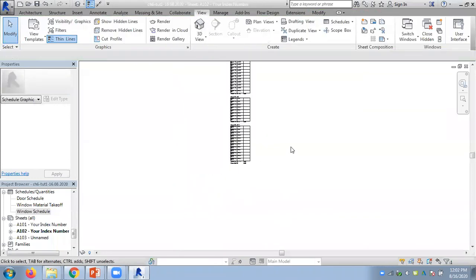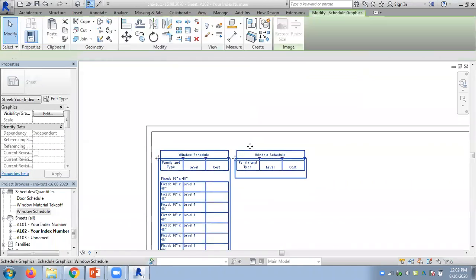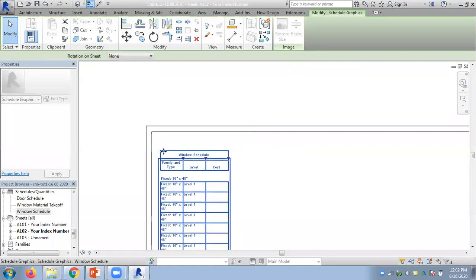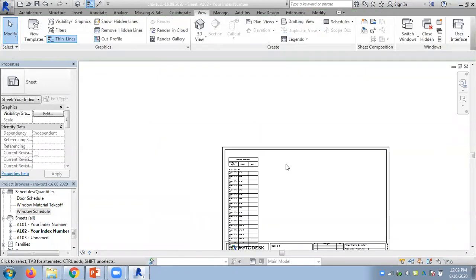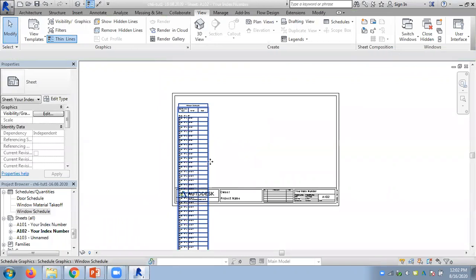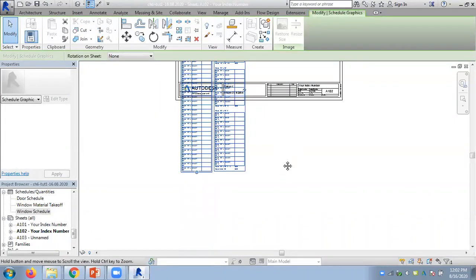Now this area is empty, but the columns will not automatically come and merge. So what do you have to do? Use this control here and drag and drop it here. Now it's finished. So this is how we get the original QS table again. Splitting is easy, but merging will take some time.